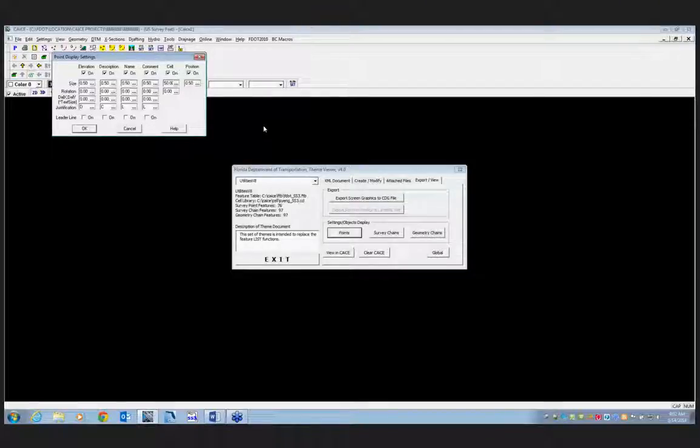Now, FDOT is currently in a transition period, and most of the styles have been set to use annotation scale, all the line styles. Guardrails are an exception. There are a few others, but for surveyors, I think that's pretty much the exception. They do not annotate with the scale. They are set to have the posts 12.5 feet apart for realistic purposes, and so roadway design has moved to annotation scale.